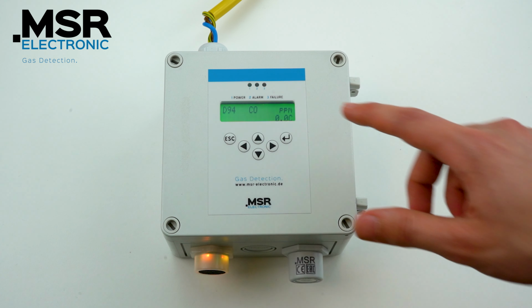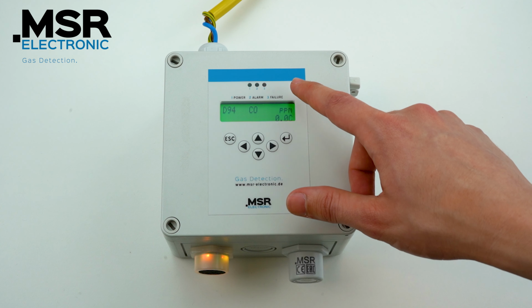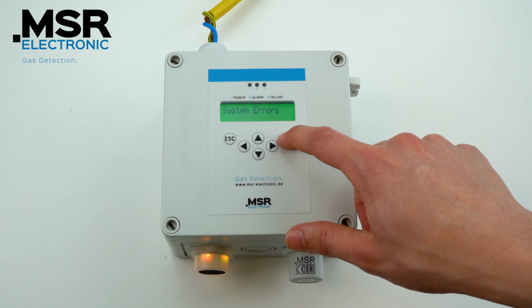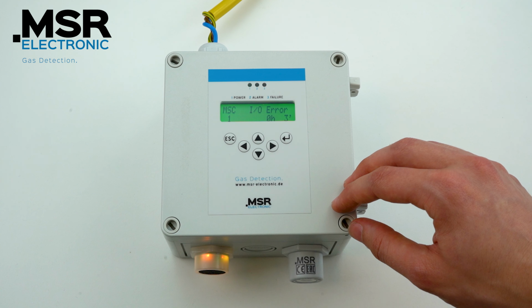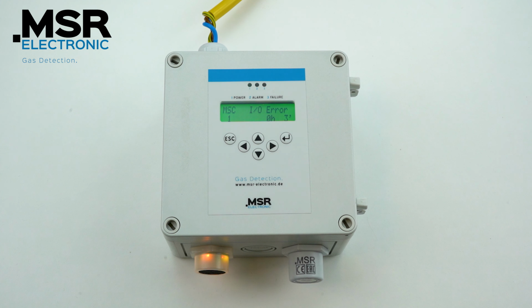There are several LEDs on the MSC display. In this case, the yellow error LED and the WAO at the bottom left of the device light up. However, the latter is not always present. If you now navigate to the error status of the controller, you will find an MP error on the one hand and an IO error on the other.